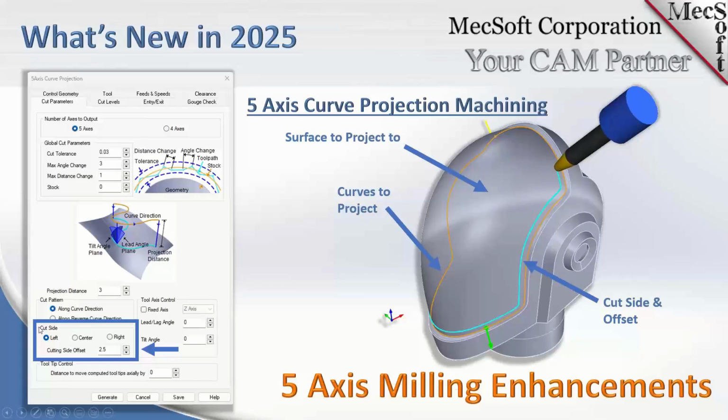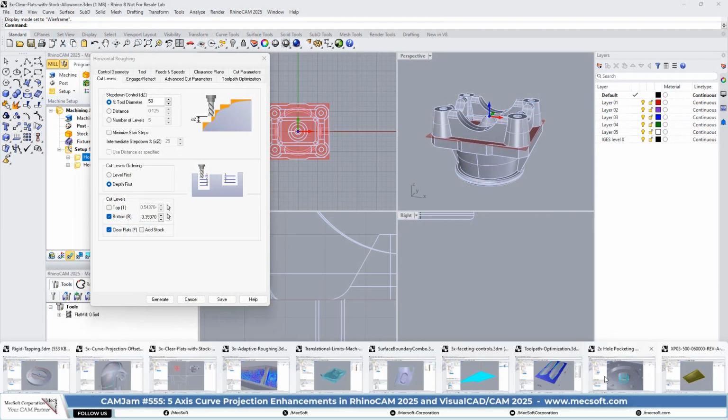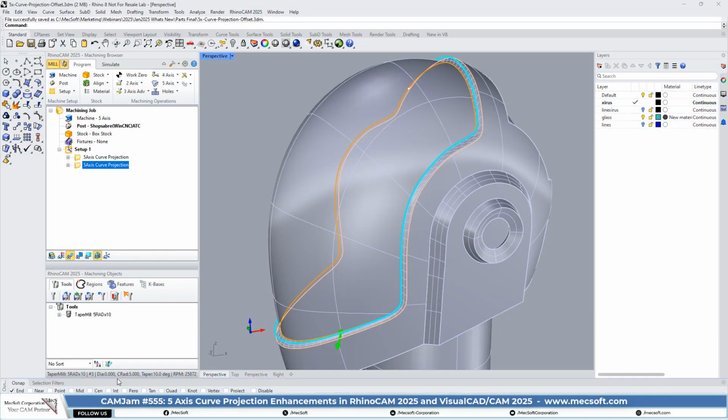And again, you've got this additional dialog here in the cut parameters tab. It allows you to set the cut side, left, right, center, and then also an offset if you want to apply an offset value. So very, very helpful if you're cutting in 5-axis. We'll go down here, go here, go over here. Now this is a big deal in 5-axis machining.